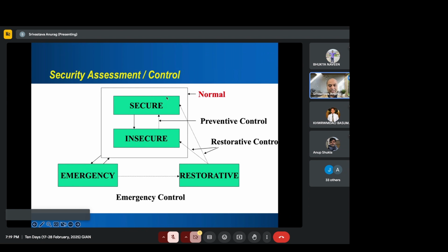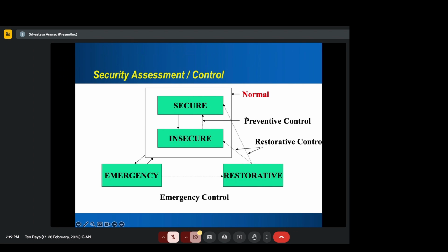If that is not the case, then because we are doing the if analysis, we have time, it has not happened in the field yet, we can apply some preventive control to make it secure again, right? So if it's not secure, which means it's insecure, for a specific set of contingency, we call it contingency. So line outage, generator outage we call contingency. So if it happens that we are not meeting the constraint, then it becomes insecure. And once it becomes insecure, we can do some preventive control before it happens to make it secure again.